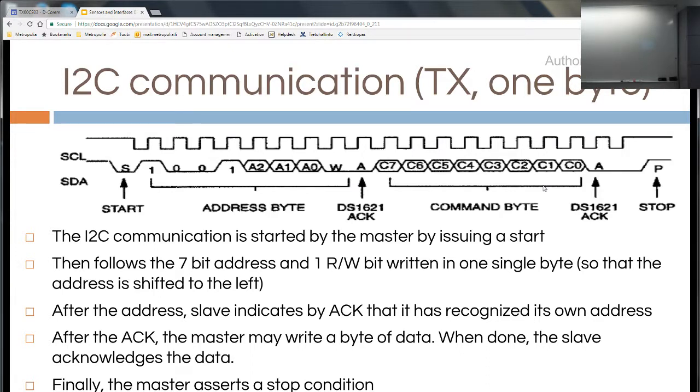This means stop. When the clock goes high and stays there, and the SDA goes high, that's stop. So basically this can be as long as needed. One place where this is used is with the EEPROM circuits in all kinds of small devices.